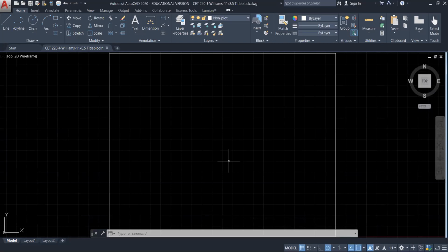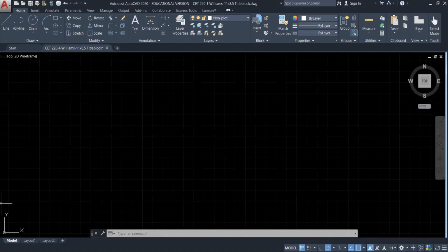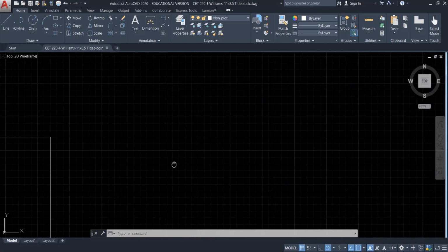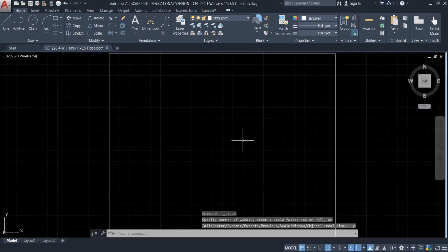And that's pretty cool because sometimes when you're drawing objects, they will be out here somewhere, and you say, "Well, I knew I drew it. Where is it?" Well, that's because it's out of the area of your workspace. So if you do a zoom extent by taking that rolling mouse button in the center and just depressing it up and down several times. Sometimes you have to be a little persistent with it, depending upon your mouse. Good. So now we just did a zoom extent.